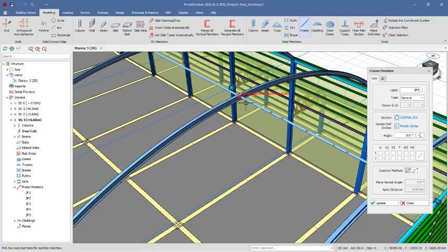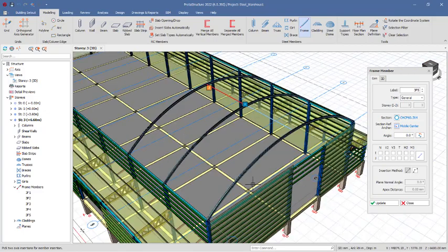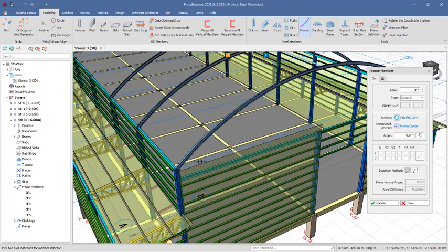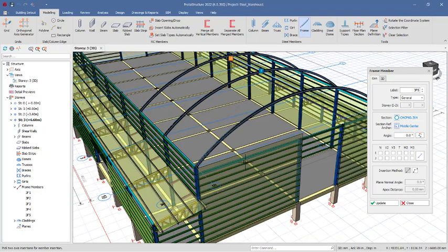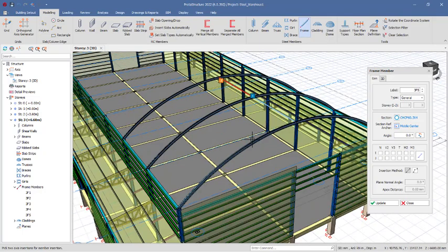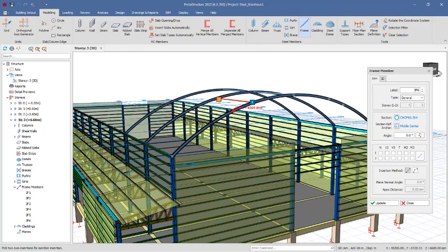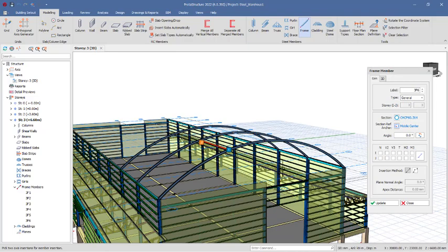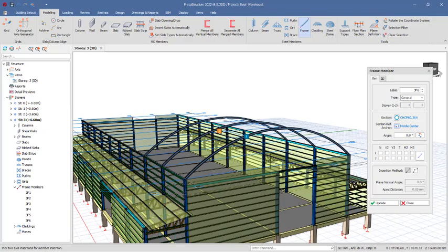You may not necessarily use this to represent your rafter, because it is not sitting right on the purlins, and you cannot manage that or distribute it as you want. If you hover around the beam, you can see some snap points. Those are the only points where you can place this. Any point that is being snapped, you can see. These are the points you can place this successfully. So this is how to place a curve beam rafter.